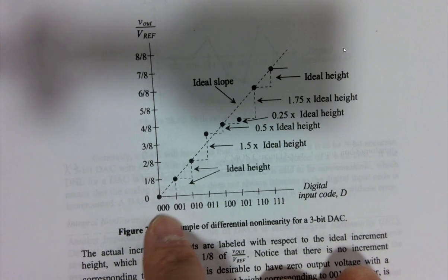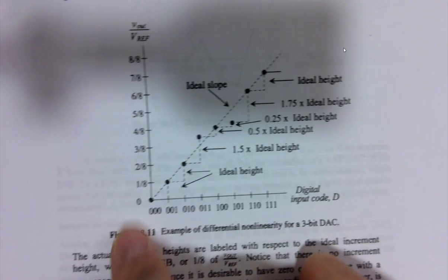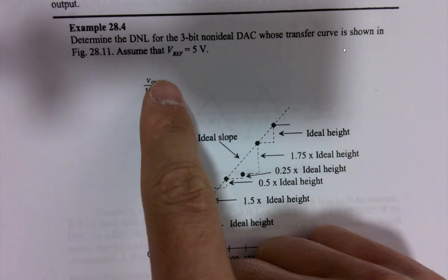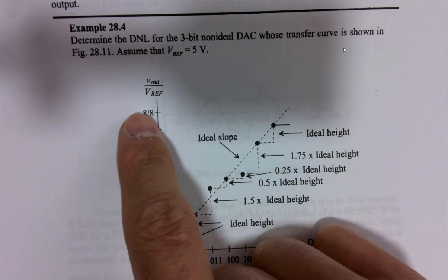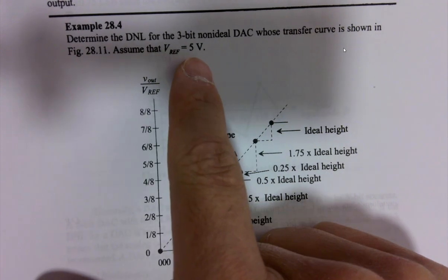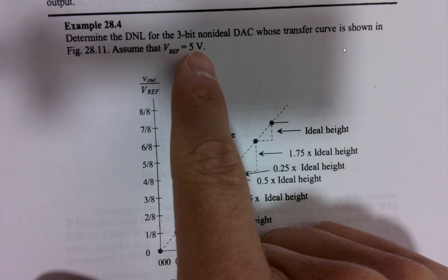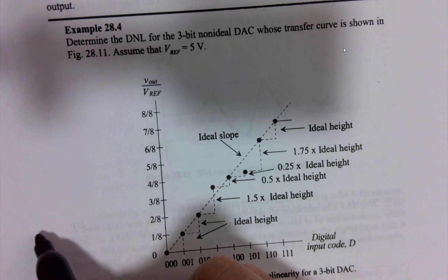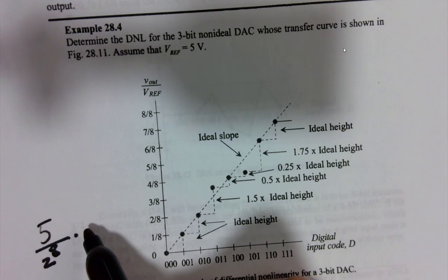Starting from 0, 0, 0, definitely you are expecting a 0 output for the analog output. So these are VL over VREF, but you can convert it to the actual analog voltage if you're assuming 5 volts, right? Yes. So how do we convert it? You just multiply the fraction. It's 5 volts divided by the whole resolution, which is 2 to the 8th, right? Yeah. And times 1.